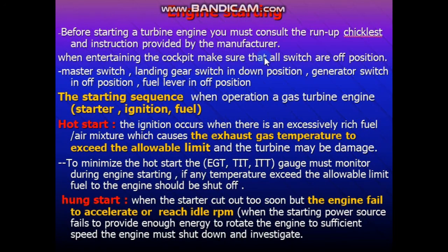After we see the video of hot start and its effect, how do we minimize it? To minimize the hot start, the EGT, TIT, ITT gauges, and we know the meaning of these abbreviations, must be monitored during engine starting.